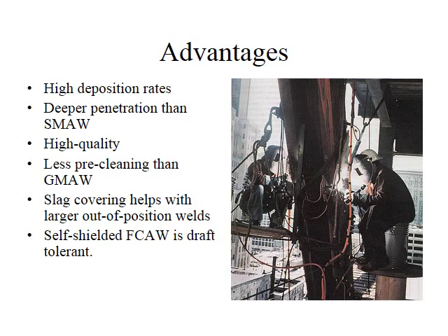Using small diameter electrode wires, welding can be done in all positions. Some flux-cored wires do not need an external supply of shielding gas, which simplifies the equipment. The electrode wire is fed continuously, so there is very little time spent on changing electrodes. A higher percentage of the filler metal is deposited when compared to shielded metal arc welding, as there are no stubs. Finally, better penetration is obtained than from shielded metal arc welding.